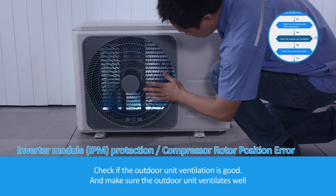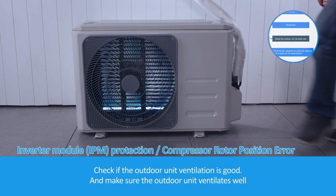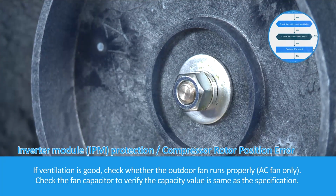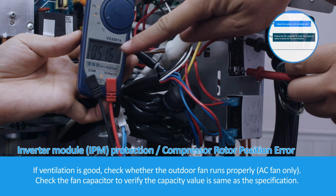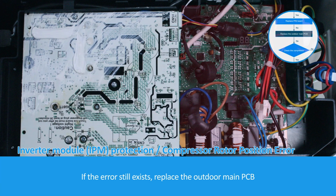Check if the outdoor unit ventilation is good, and make sure the outdoor unit ventilates well. If ventilation is good, check whether the outdoor fan runs properly, AC fan only. Check the fan capacitor to verify the capacity value is the same as the specification. If the fan is normal, replace the IPM board. If the error still exists, replace the outdoor main PCB.